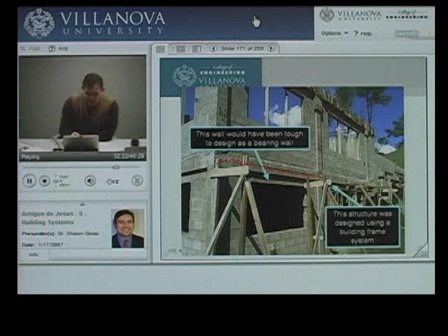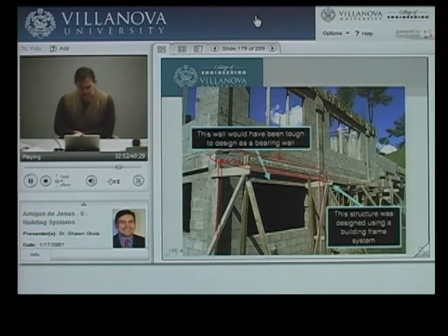So if I look at the load from the wall comes down, the load from the chapel comes down, and it's basically distributed out to this particular beam. So we're using, rather than a wall, a beam to transfer the loads out to a column over here and a column over there, which then take the load down to the foundation. So this is an example where the choice became fairly easy because of the architectural requirements with those large windows.